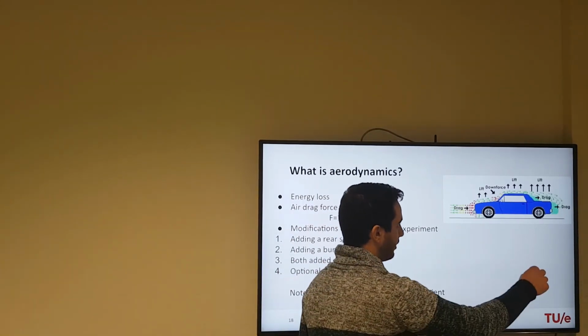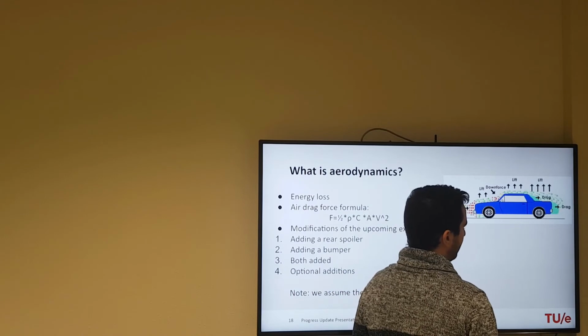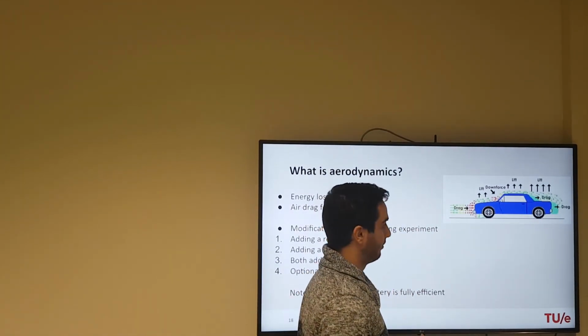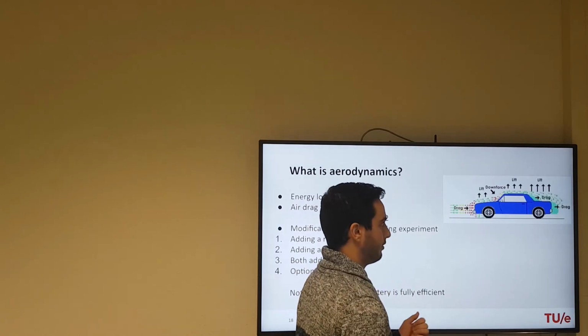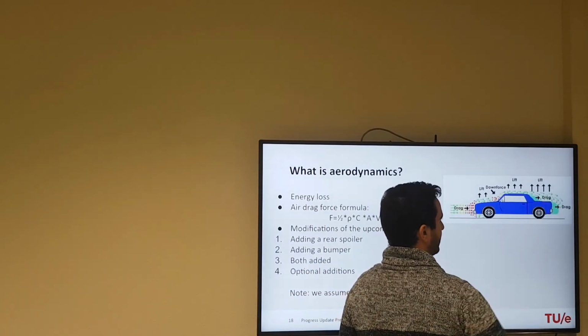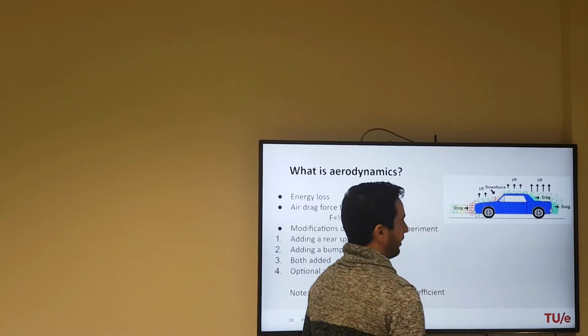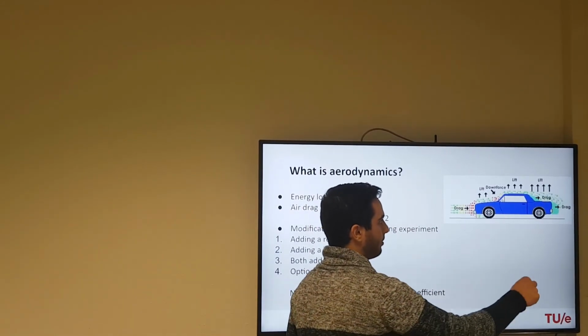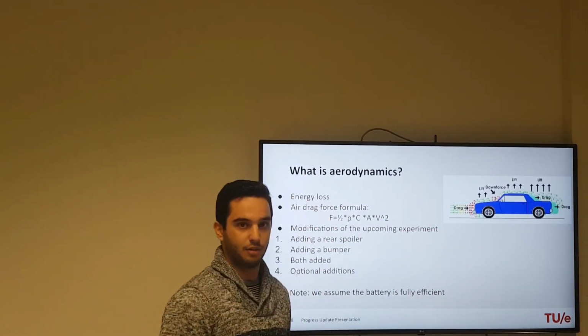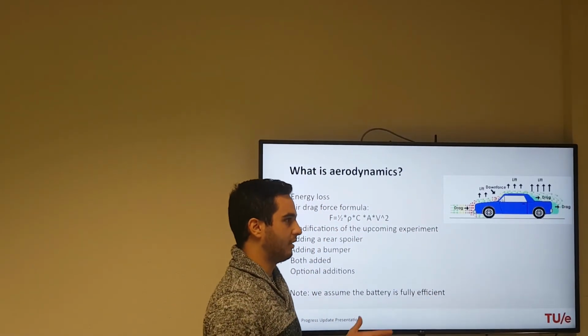As we can see here, flow separation is one of the main forces that are slowing the car down, except for the front drag. Therefore, we would like to decrease this as much as possible. So, we're going to add duct tape in order to make the body smoother, like a teardrop, which is the most aerodynamic shape in existence.